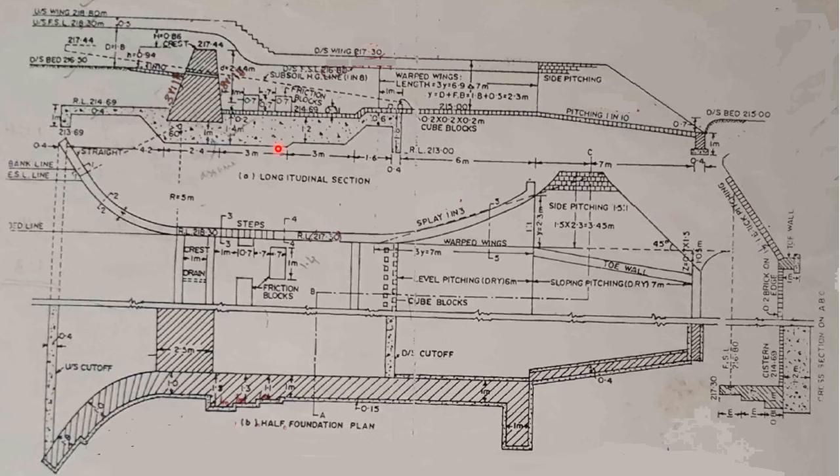Then these are the different thicknesses of floor that we have designed. See, at A, that is the toe of the crest. Here was our point A. Then here after 3 meters comes our point B. Then this is point C. So at these points A, B, C, we know that the thickness is different. That thickness should be shown here, here and here. Then these are cube blocks that we have also designed in our numerical design, also for dissipating energy.